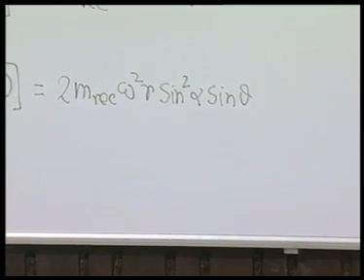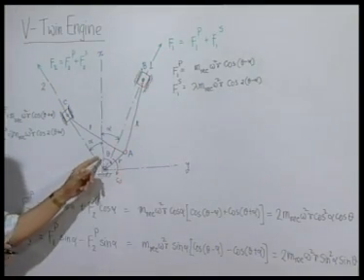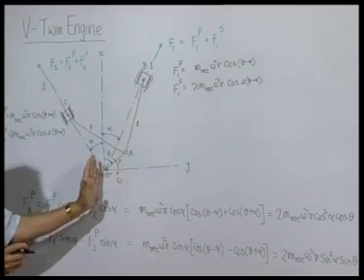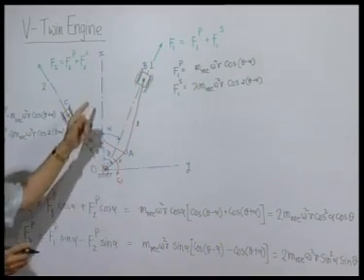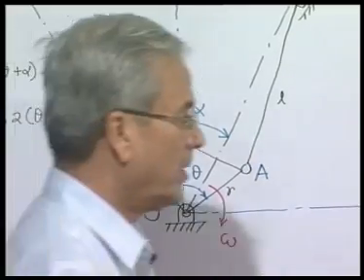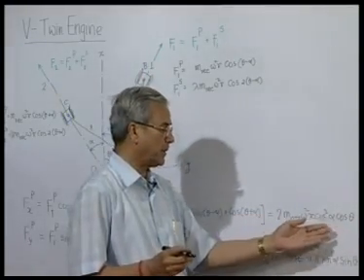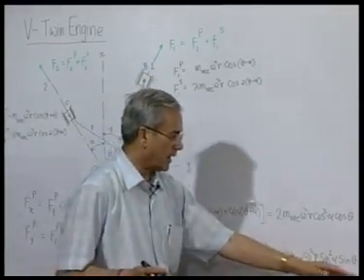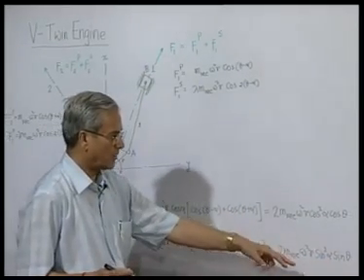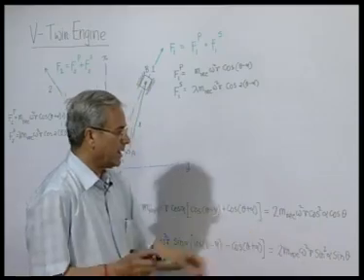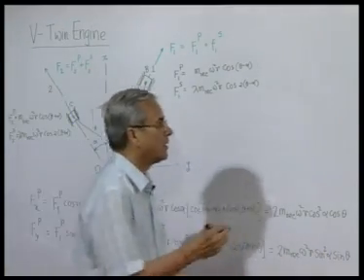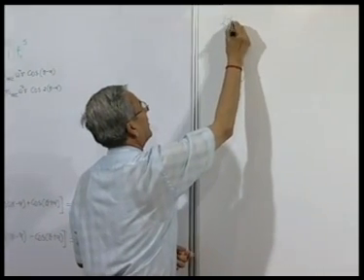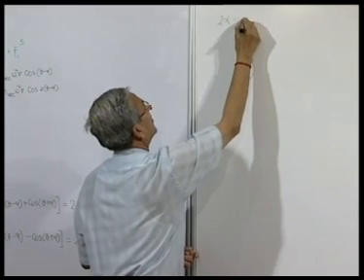So, the whole primary unbalance, as you can see, since theta when it is rotating with a constant angular velocity, and if we consider that theta at t is equal to 0, the common crank was aligned with the x axis, then theta is nothing but omega t. So, it is a harmonic function of time, that means a fluctuating unbalanced force in the x direction, and in the y direction there is again the unbalanced force, which is also fluctuating with the same frequency. Now, you can see that there can be one special case where 2 alpha is equal to 90 degrees.